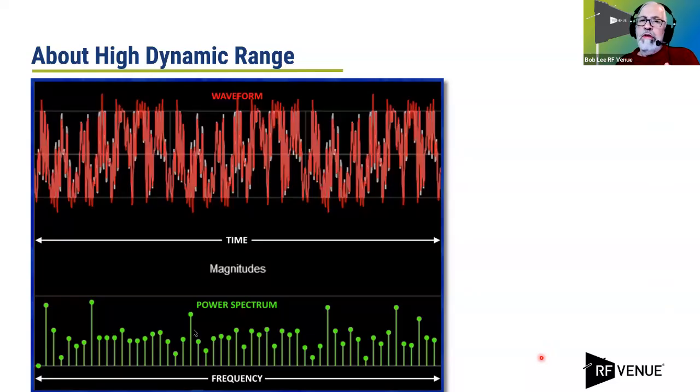Now, these frequency coordination services, one I should have mentioned also is Wireless Workbench from Shure. These will do the calculations. It's just simple addition and subtraction to figure out frequencies that will work well with each other so that intermod products are not likely to conflict with any carriers that you're trying to use.